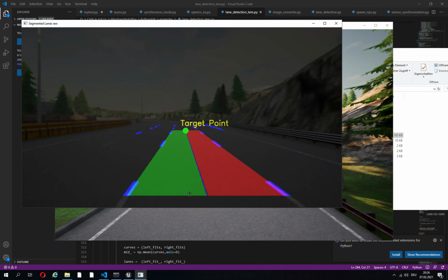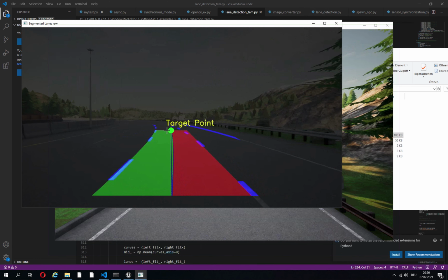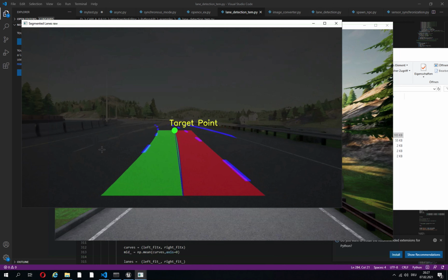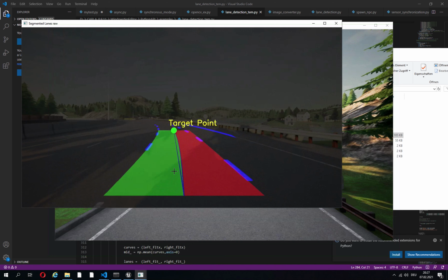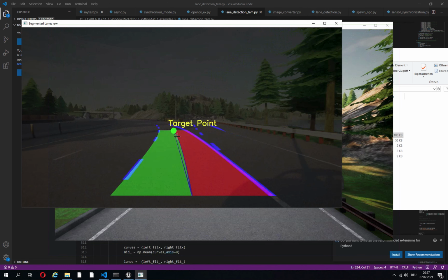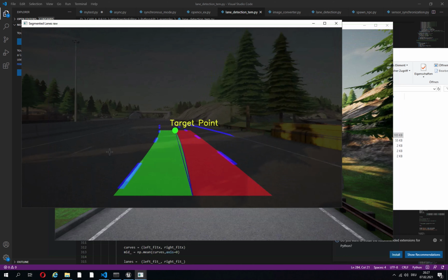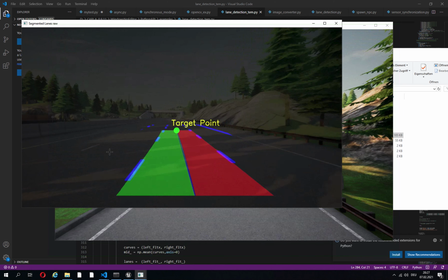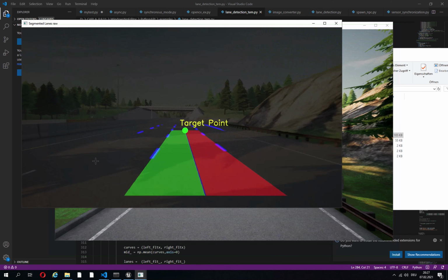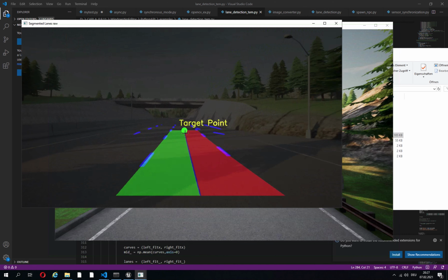And here we see our left and right region, and this is our middle curve, and this is our target point. So now we get to a sensitive place where I was telling you that here comes the role of the correction parts, either using sensor fusion or, here it did very well actually. I was afraid that it won't work right. But here is where the sensor fusion could be playing a role, just to avoid sharp changes in the position of the target point, for example.